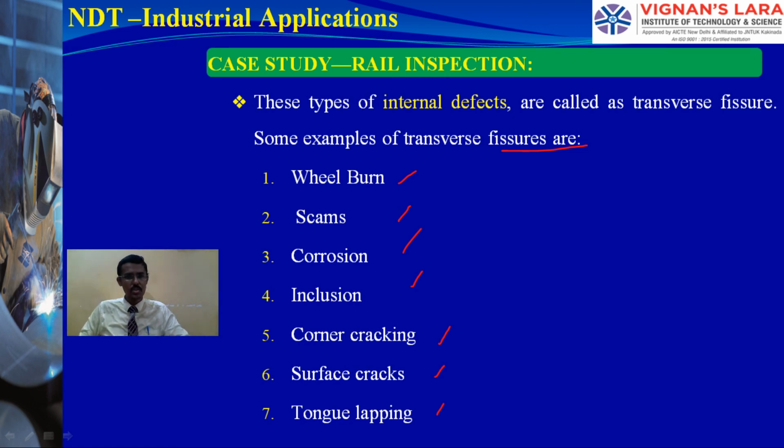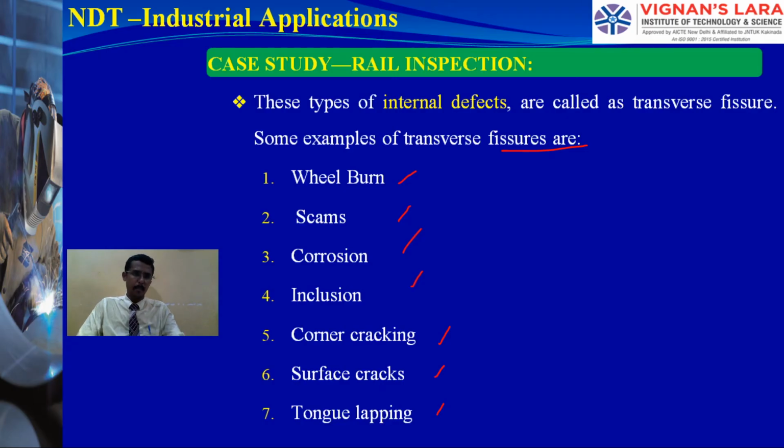Then there are welding inclusions. You know, tungsten inclusions during welding may come, or slag inclusions during welding may come, or maybe the corroded zones are not properly cleaned on the faying surfaces of the V grooves. So there are chances, and these chances are to be monitored periodically.